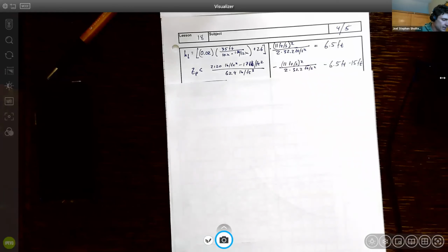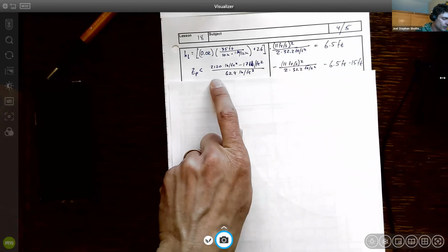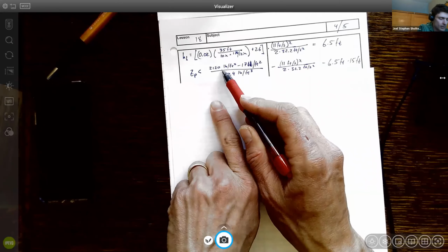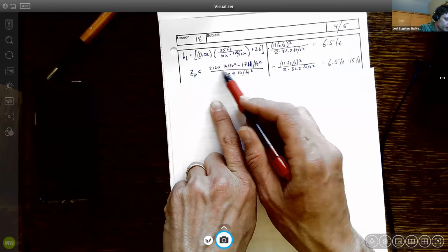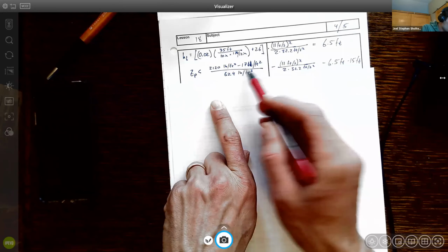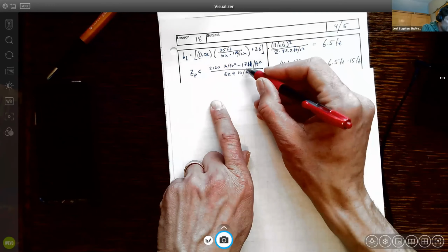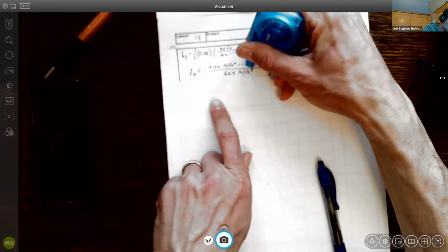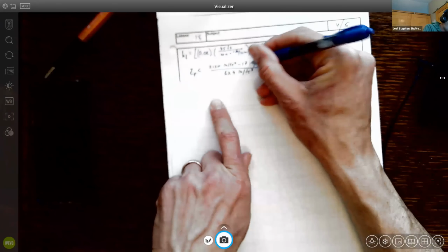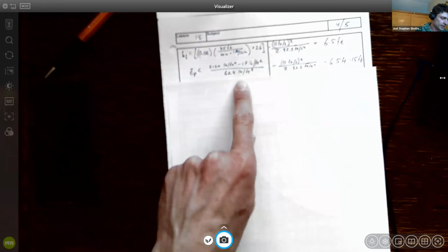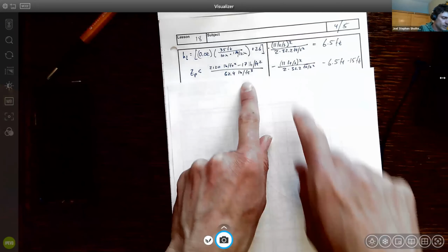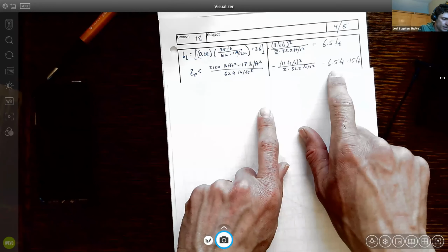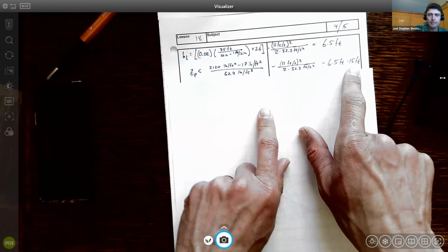So now we can plug everything in. Our height of the pump needs to be greater than the atmospheric pressure, 2,120 pounds per foot squared, minus our vapor pressure, which is 17 pounds per foot squared, and then divided by our gamma, 62.4 pounds per foot cubed, minus velocity squared over 2g, minus our head loss in the pipe, minus our net positive suction head, which was given.